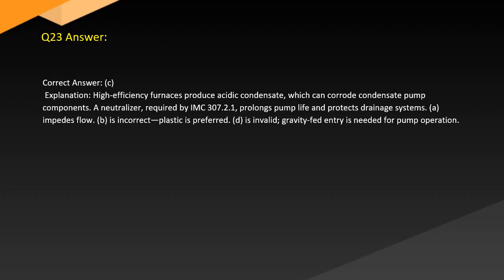Answer. Correct answer: C. Explanation. High-efficiency furnaces produce acidic condensate which can corrode condensate pump components. A neutralizer, required by IFGC 307.2.1, prolongs pump life and protects drainage systems. A impedes flow. B is incorrect. Plastic is preferred. D is invalid. A gravity-fed entry is needed for pump operation.